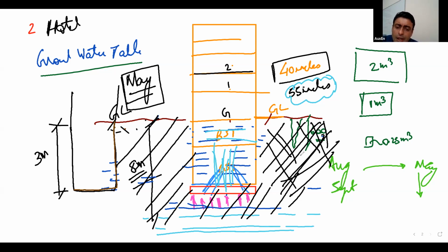Every structural engineer worth his or her salt knows that there is a problem of black cotton soil in Indore, and there has to be adequate design consideration for these swelling pressures.